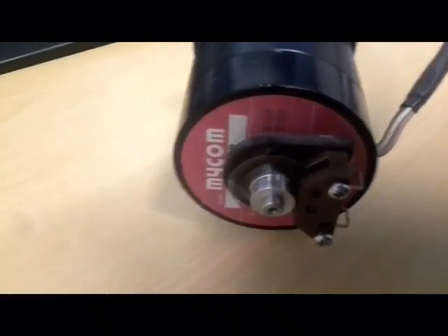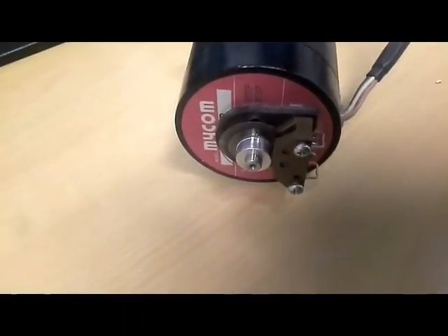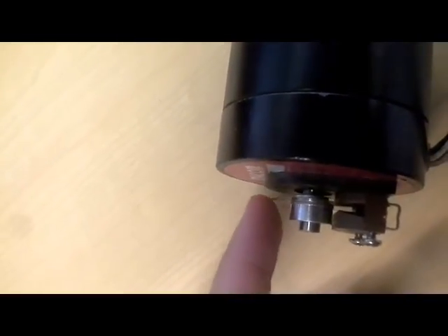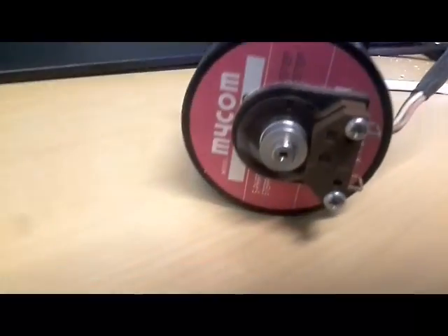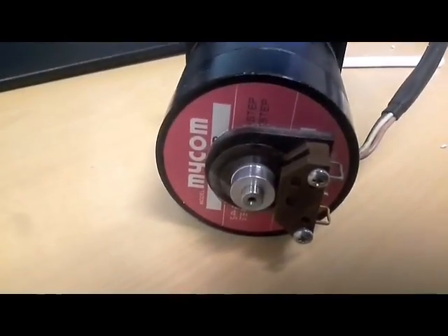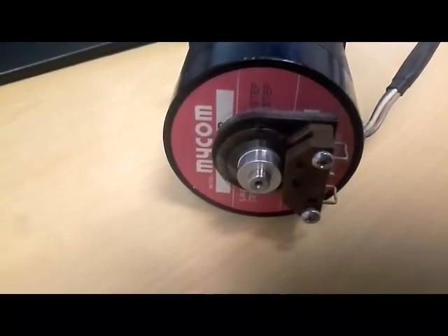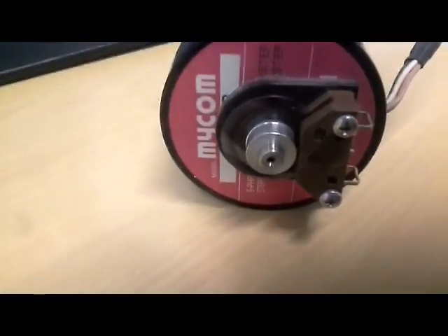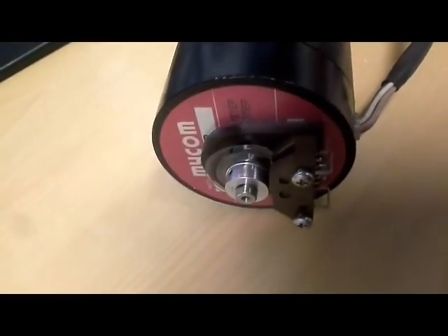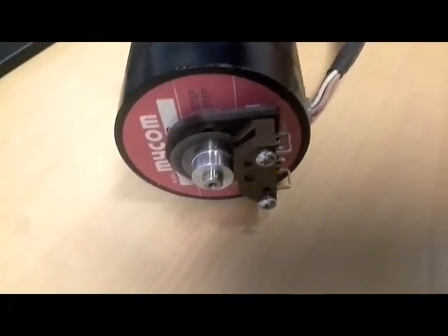An optical encoder is an optical sensor that's used to measure rotational position and rotational velocity. If we look inside of this encoder, you'll notice that there is a little disc right here. It's a plastic disc, and if we were able to zoom in much farther than we're able to right now, we would see that there are little black marks positioned all in a circle around this plastic disc. The plastic disc is attached physically to the shaft of the motor, so you can see that if I turn the shaft of the motor with my fingers, this plastic disc also rotates.